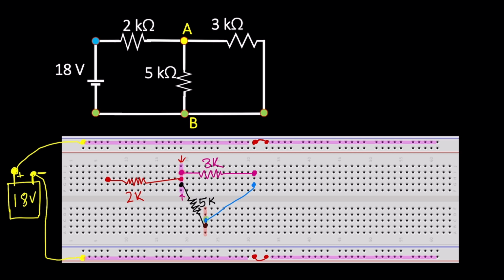Okay, now you can see here we need to connect the voltage source in this particular circuit, right? The 18 volt voltage source needs to be connected to the 2 kilo ohm terminal 1. Okay, so I take a wire from this point and connect it to this one, the connector line. Here you can see that all the connector line pins are the terminal 1 of the 2 kilo ohm resistance. Okay, that means we already connected the source with the 2 kilo ohm resistance, right?